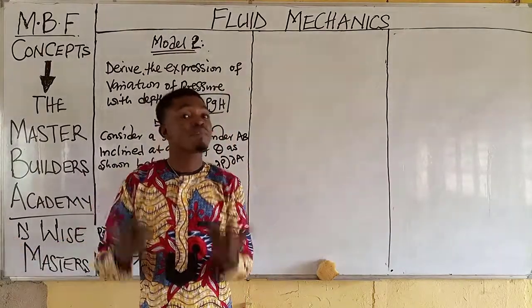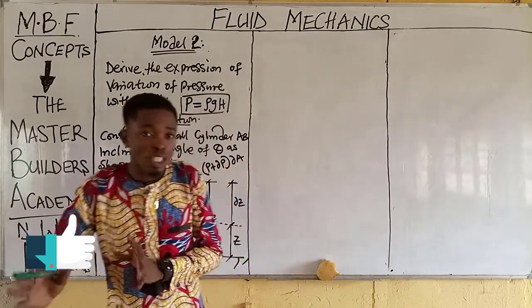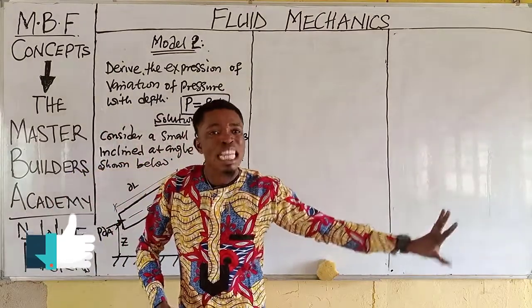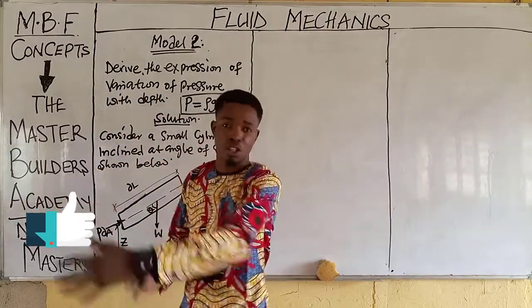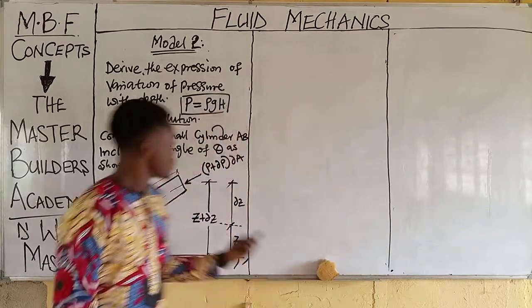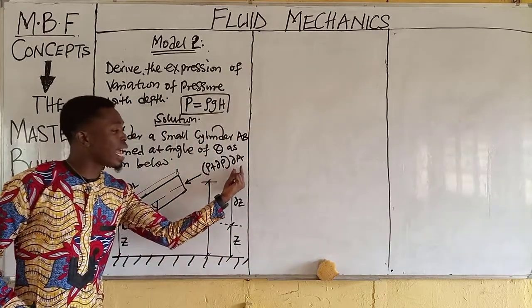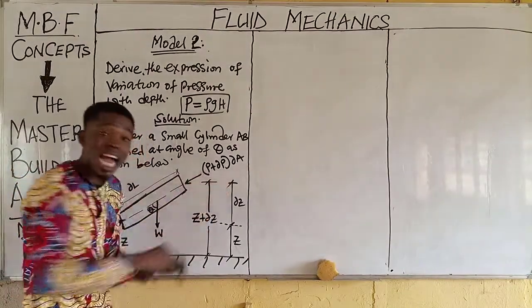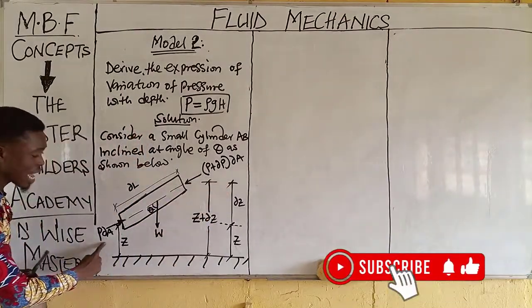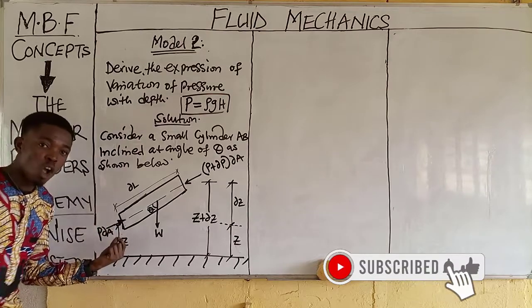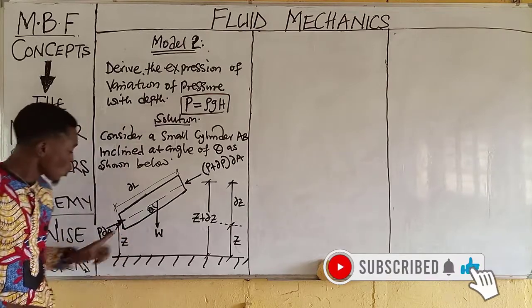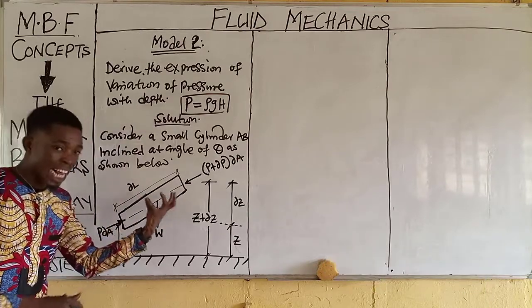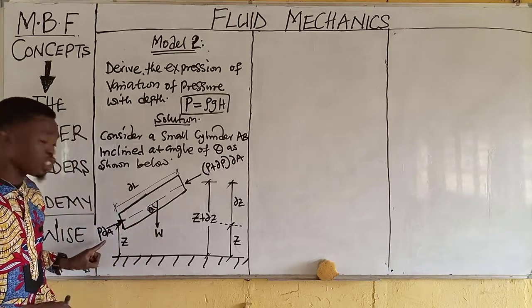Therefore, we find a relationship where pressure relates with another vector quantity that can be resolved. Pressure multiplied by A gives us force. So indirectly, we have this as a force, and similarly, we have this as a force. So at the first end, or the entry end, we have P multiplied by the area. Now, why are we using changing A?